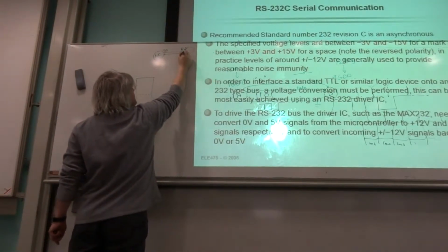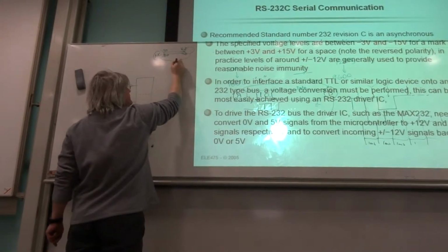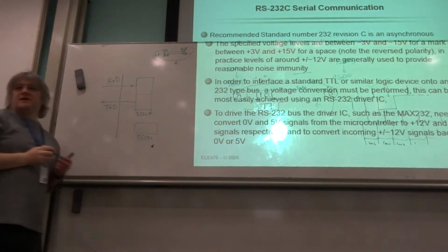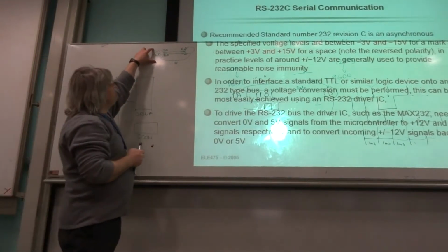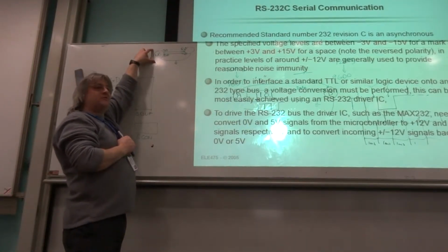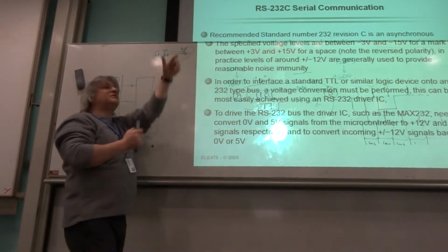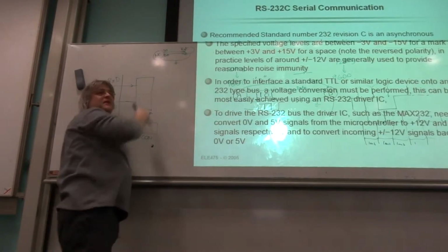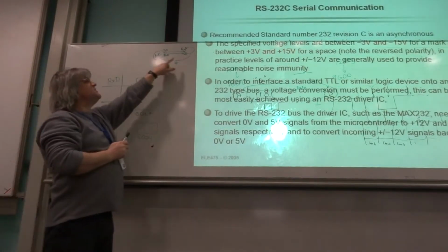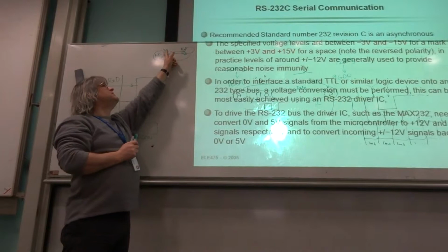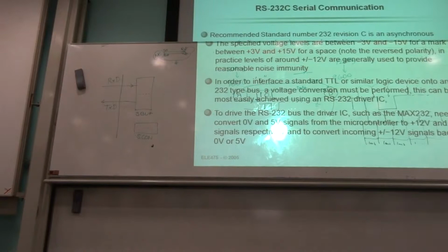In the other direction, you'd have the TXD here wired up to the RXD on this one, and then you'd have some kind of shared ground wire between them. To build your complete bidirectional communication system, we need 3 wires. 1 wire for communication in this direction, 1 wire for communication in this direction, and then some kind of ground reference point. And between the 2 8051s or whatever it is, you could be receiving data and transmitting at the same time. That's why it's full duplex.